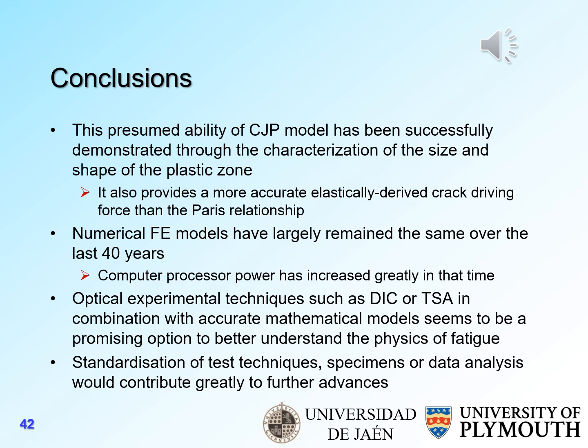Considering numerical FE models, the way they model cracks has largely remained the same over the last 40 years, despite the fact our processing power has increased very dramatically in that time. Optical techniques such as DIC or TSA in combination with accurate mathematical models seems to be a promising option to better understand the physics of fatigue. And standardization of test techniques, specimens and data analysis would contribute greatly to making further advances. Currently the data is extremely scattered, and when you try and repeat experiments yourself, they don't always give the same answers as reported in the literature.